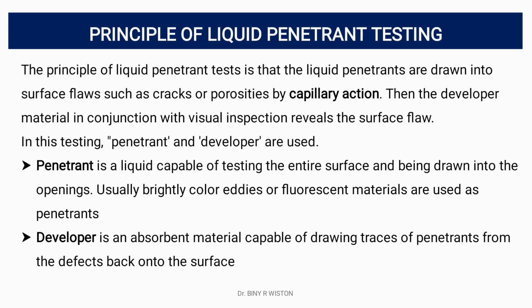So the principle of liquid penetrant testing is the penetration, or the ability of a liquid to wet the surface of a solid workpiece or specimen and flow over the surface to form a continuous and reasonably uniform coating, thus penetrating into cavities that are open to the surface.